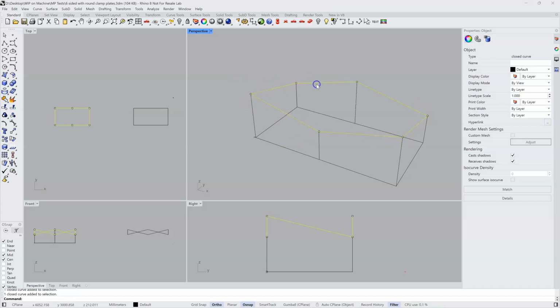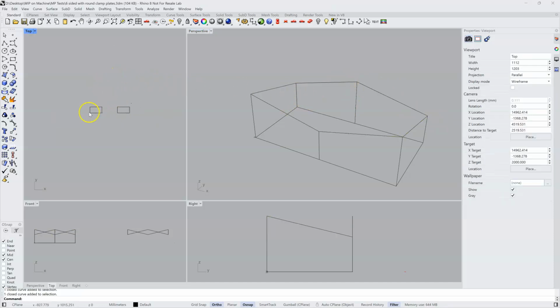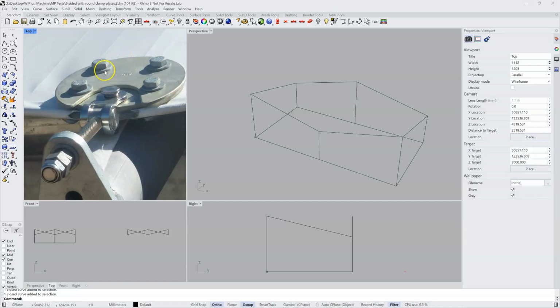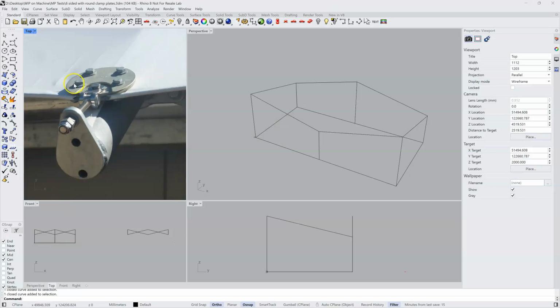the poles. In this example, we're going to use a sail that uses a single cable around the outside and round clamp plates. And we're going to use clamp plates that are similar to this style with some sort of tensioning device. This could be a toggle bolt or a shackle and a turnbuckle.